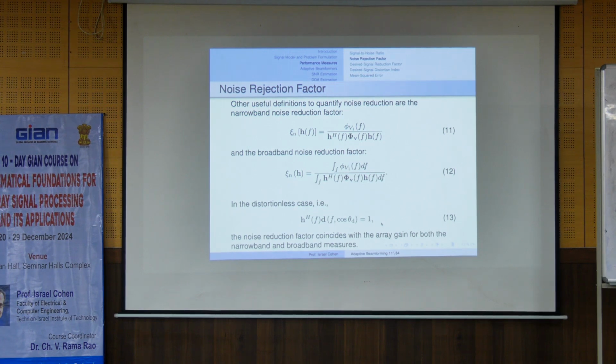With multi-channel signal enhancement, we didn't have such a constraint all the time, only for distortionless response, which means MVDR, LCMV, GSC. Here, because we work with direction, which means we work with a beamformer, we always use this constraint. We keep it for the distortionless.